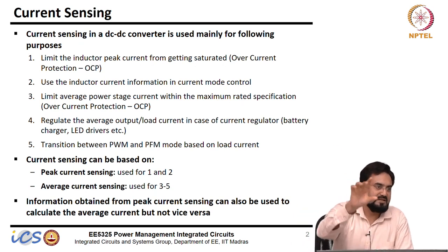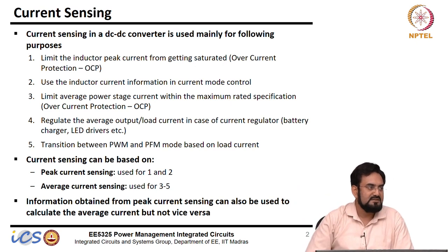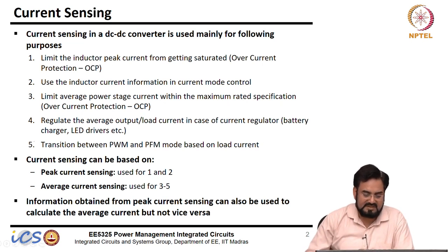You cannot just apply a constant voltage and say, okay, the LED will light up. Even a small change in the LED voltage can cause a very large change in the current, which means your brightness will change and it may even heat up, even if you change the voltage by 100 millivolts or so. That's why it always requires regulated current.